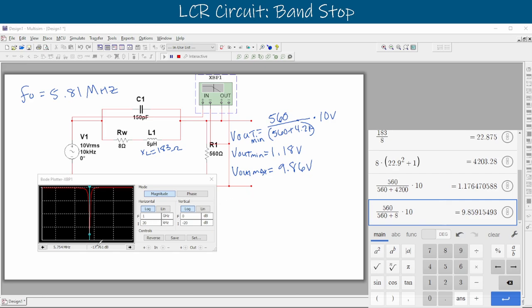So in this one, we now found out our voltage gain. This is going to be the gain of it. And we use V gain is equal to 20 log of our voltage out divided by voltage in. And that's what this Bode plotter is doing. It's got an input and output, and it's comparing its input to output, and it's giving you a decibel value for it on a logarithmic scale. And so we are going to use this equation, rearrange it, because we just got the gain. We just got 17.761. Technically it's negative there. And that is equal to our 20 log of an unknown V out divided by our V in, and we know that that's 10 VRMS.